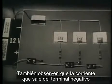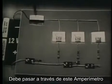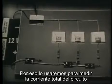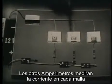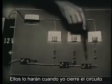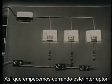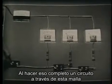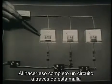Also notice that the current leaving the negative terminal of the battery, all of the current must pass through this meter. Then we'll use it to measure the total circuit current. The other meters will measure the current in the individual branches. Now, it'll do that when I close these switches, of course. So let's start by closing this switch. By doing so, I complete a path for current through this first branch.